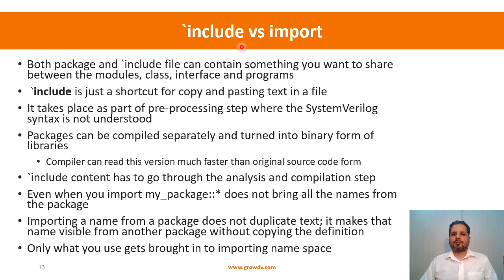We'll look into the difference of tick include versus import. Both the package and tick include can contain something that you want to share between module, class, interface, or program. Both of them can be used. Okay, but let's understand what is the difference and why packages are suitable in certain cases over the tick include. So tick include, as we have seen, is just a shortcut to copy pasting the text in a file, and it takes place as a part of the pre-processing step, okay, where the SystemVerilog syntax is not understood. So this is an important point that you might want to keep in mind.